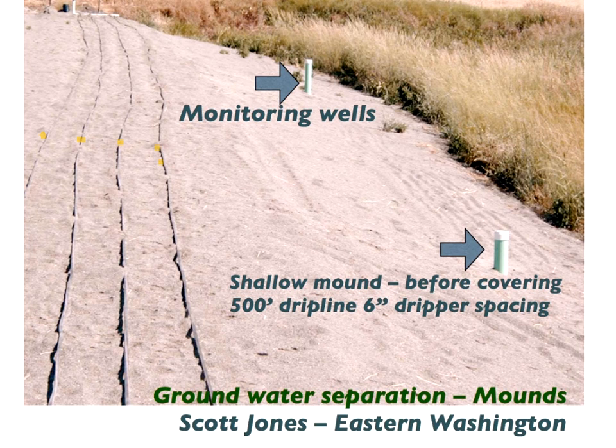So we have 1,000 drippers feeding the sand, so there's very little distance between the drippers, so we don't need much lateral movement for it to saturate the sand and obtain the maximum treatment, the maximum amount of oxygen contact, the maximum amount of treatment by the bacteria in the soil, the aerobic bacteria with the oxygen in the sand.